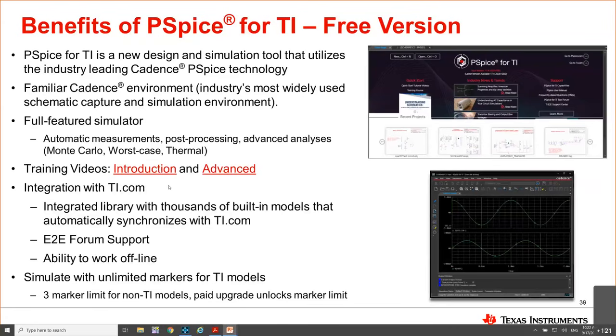There's integration with TI.com, and this is a really big one, that there's an integrated library with thousands of built-in models that automatically synchronize with TI.com. There's E2E forum support, so you can go online to the E2E forums and ask questions about pspice-for-ti or your circuit that you've built. There's the ability to work offline, and you can use unlimited markers for TI models. There is a 3-marker limit for non-TI models, but you can pay to upgrade to unlock the marker limit. But as long as you stick with the TI models, no marker limit.